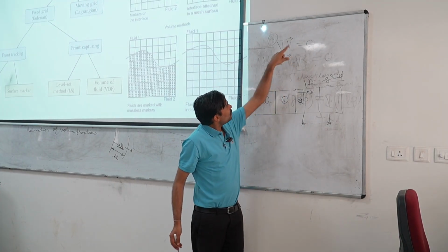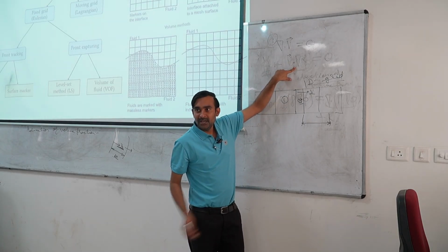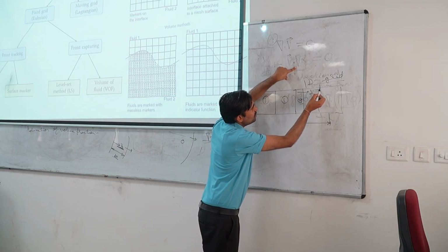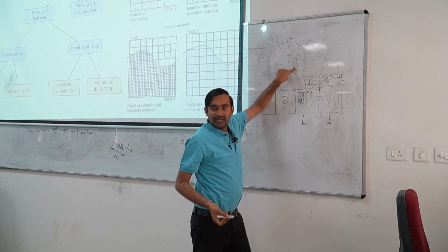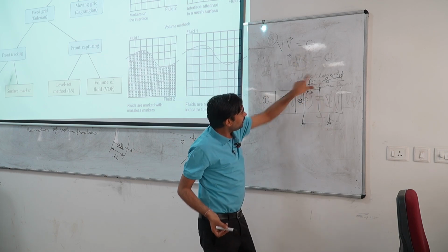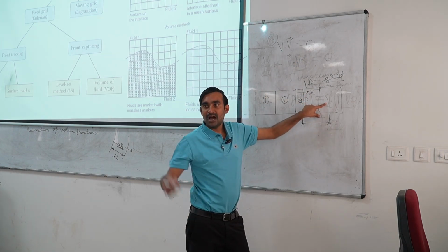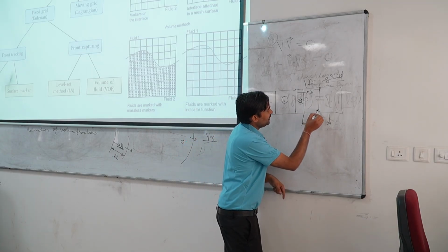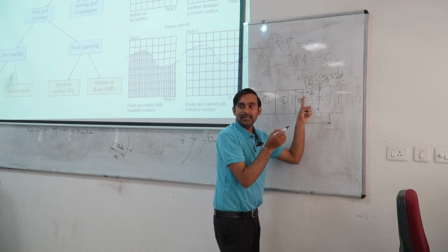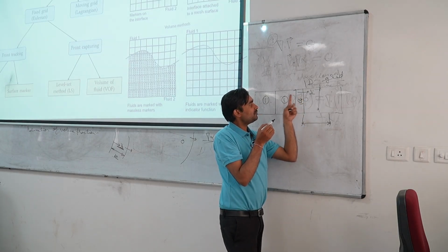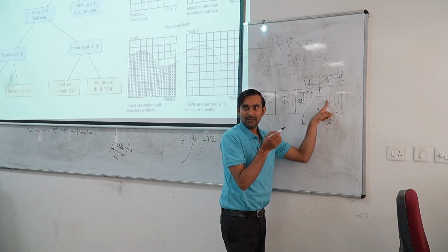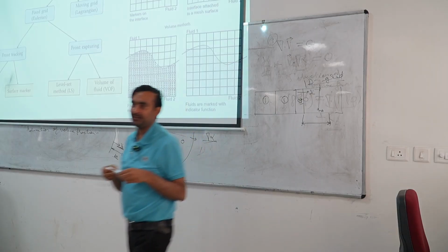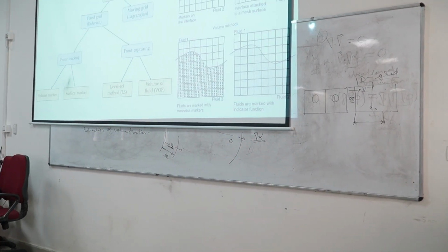When I will be solving this particular advection term, I need to calculate how much flux will be transporting from this boundary to the next boundary. While I am defining the flux calculation for this, I have to define it in such a way that till the time the interface is reaching this boundary, the value of flux of the reference phase, or flux of alpha, should be 0. Once it is crossing the boundary, then only there should be some positive flux of this quantity.